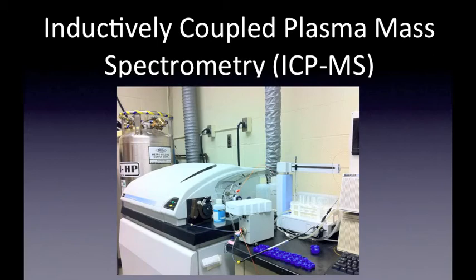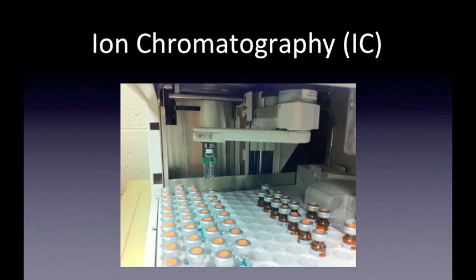In our project, ICP-MS is used to determine the concentration of arsenic and iron. Ion chromatography is a form of liquid chromatography. Ionic species separate differently depending on the species size and type. Sample solutions pass through a column, where ions are absorbed by the column constituents. The retention time differs for different species, and thus determines the concentration in the sample. We use the IC to measure the acetate, chloride, nitrate, and sulfate concentration of our samples from different parts of our reactors.